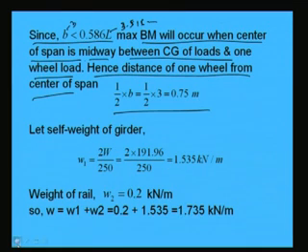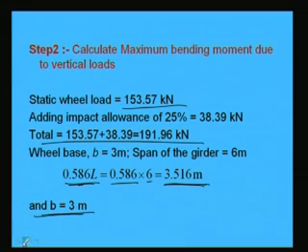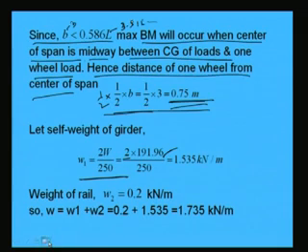Now, other things we have to calculate. So this is how 0.75 meter has come, right. Now the self weight, as we have considered earlier, is 2 W by 250. So 2 into W was given, W we have calculated here. So from this we can find out 2 W by 250. The self weight has been assumed as per the discussions in the earlier lecture. We have seen that it will be 2 W by 250. So W has been calculated earlier, and from that we can find out the self weight.